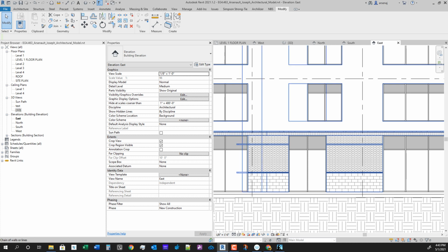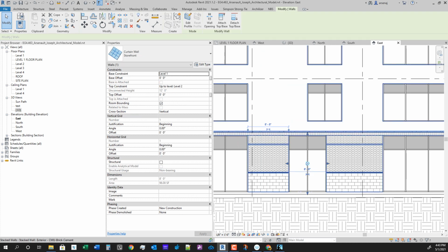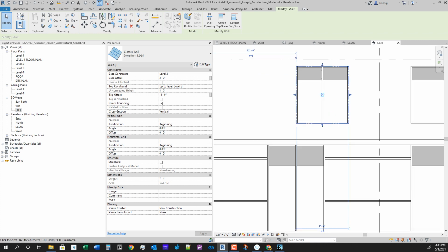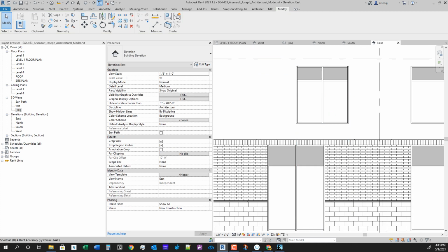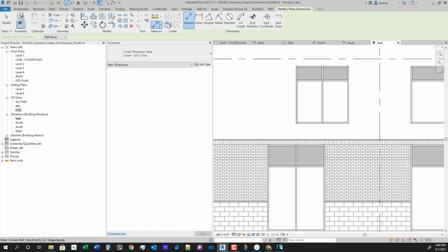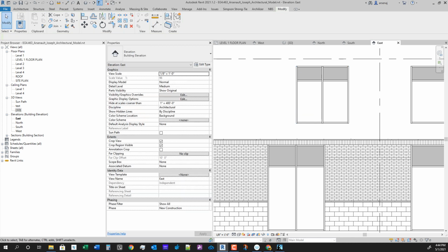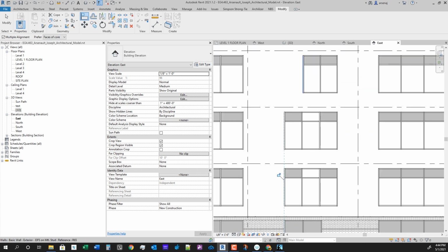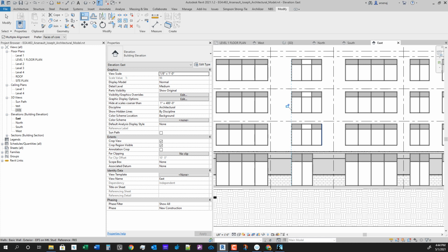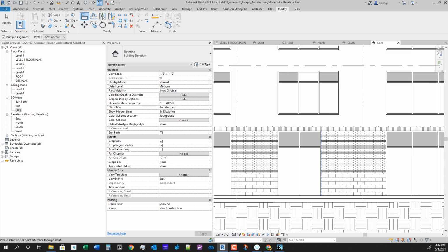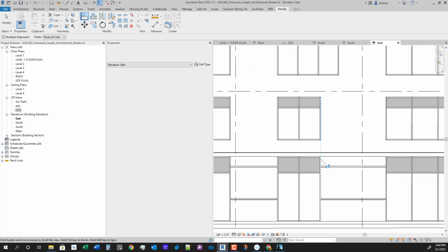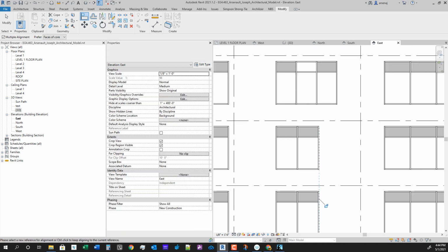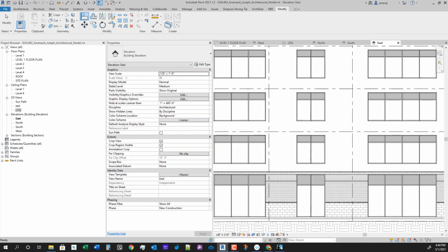And so now we would just need to align with the windows up above. Got these 8-foot windows. Just going to take a quick dimension to make sure that these are... oh, see there's a 7'4", so let's use our align command and multiple to align like we did on the front side. Being careful to align the curtain wall, not the wall. So you do that by tabbing and get that dashed line by holding your mouse over the edge.